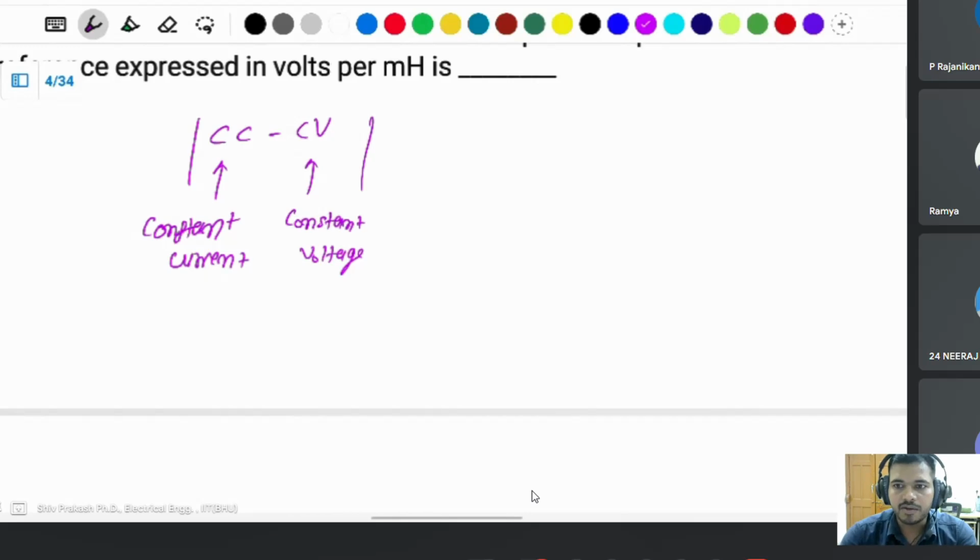It depends. In the starting, if you want to charge a battery, there is a fully discharged battery. You want to charge the battery in a very short time. In modern times, a lithium ion battery can be charged at 10C, approximately; 2C, 5C is also there in the market.